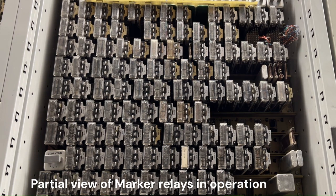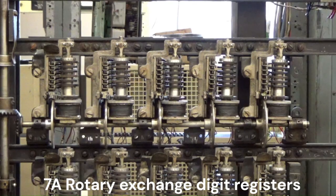Importantly, the talking path switching action occurs asynchronously from the dialing time. Bottom line, making a call uses common control apparatus momentarily, then returns it to the shared pool. This method proved effective, for many reasons, and was used by different exchange types worldwide for over 60 years.